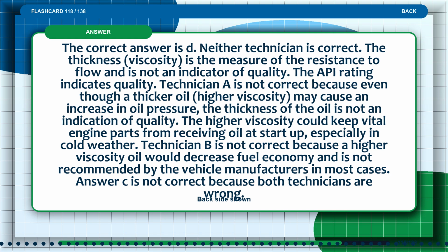The answer is. The correct answer is D. Neither technician is correct. The thickness, viscosity, is the measure of the resistance to flow and is not an indicator of quality. The API rating indicates quality.